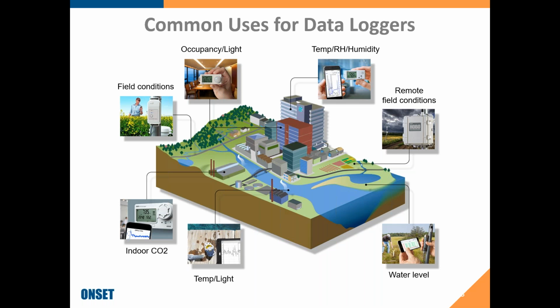That is showing you a picture of an indoor data logger that will record temperature and relative humidity in a building, under floors, in the ceiling, anywhere you want to get that data. If you have the app on your phone and you're within a 100-foot range, it is going to find it on your smart device and show you that data screen where you can save that data. So once you've deployed this in the building, you're going to set it to record, and you're going to see that data.